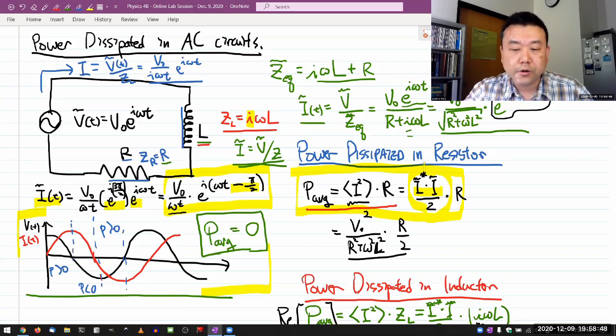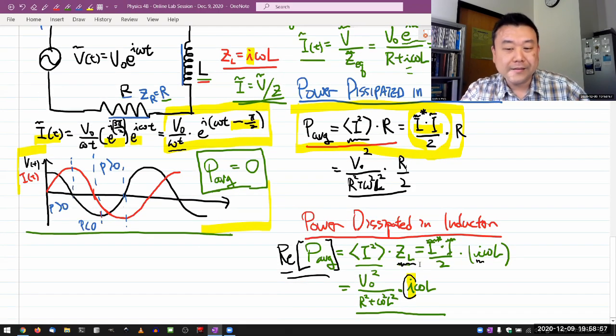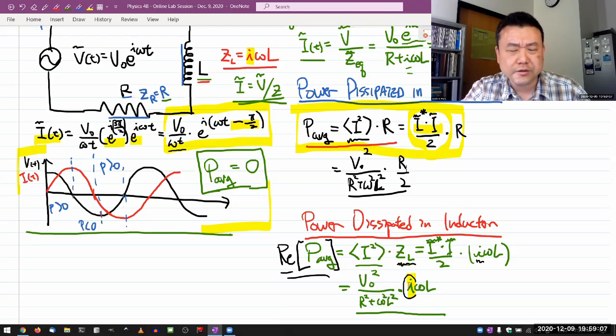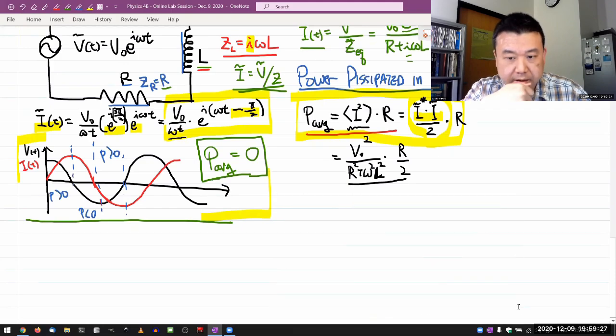And if you were to attempt a calculation like this, then this imaginary thing will hopefully tip you off that something's wrong here. You look up whatever reference you need to realize that, oh, there's no such thing as power dissipated in an inductor. If there's power dissipated in a real motor, then it's dissipated in the portion that's modeled as the resistance of the motor. So what I want you to end here with is a scenario that can help us figure something out.